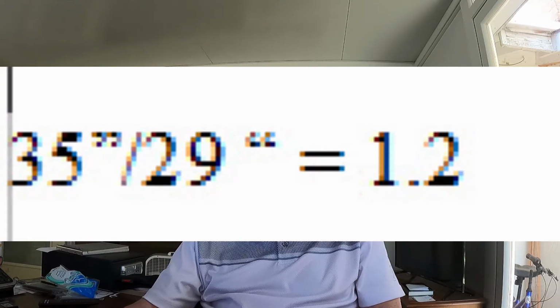If we put a 35-inch tire on this vehicle, which I did, what does it do to the torque requirements in relationship to the factory loads? Well, it's easy to calculate. 35 inches divided by 29 inches equals 1.2. This means that in order for the 35-inch tire to develop the same amount of traction as the factory tire, it requires 20% more torque. Let that settle in. The entire drivetrain was not designed to carry this extra load.